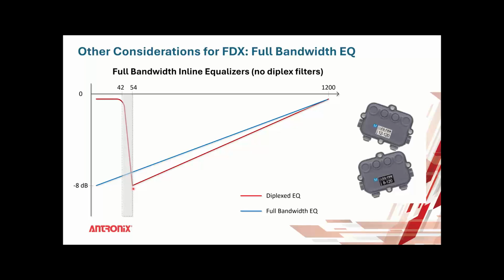As a signal travels down a cascade, the cable slope has higher attenuation at higher frequency. So as you travel down, you will have a slope that increases as it goes down the cable line.